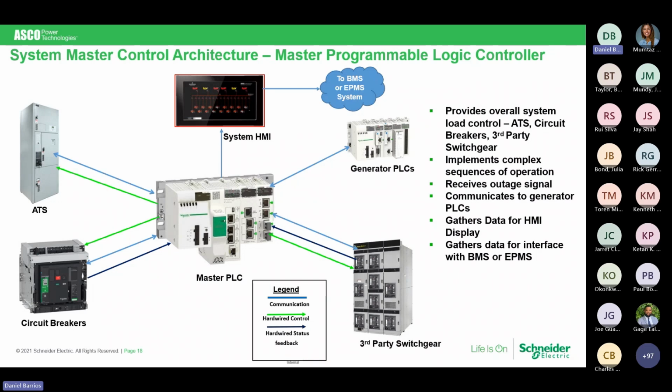If you are an IBC code building, an International Building Code, if you are considered to be a high rise building, 70 feet or more above grade, that's as high as a fire truck can reach, you are required to have the remote annunciators in the fire command room for all of your transfer switches also. Please look into that if you're not familiar with that.